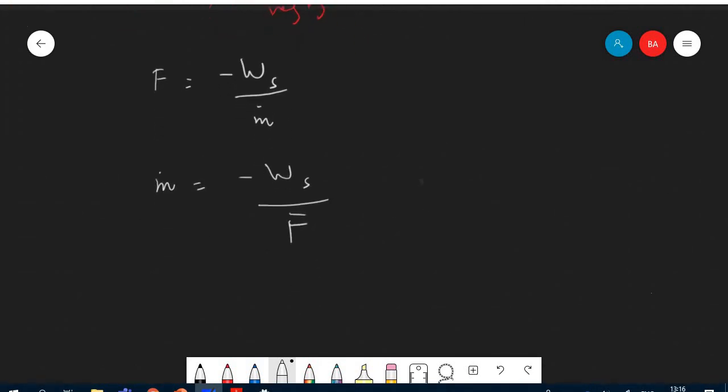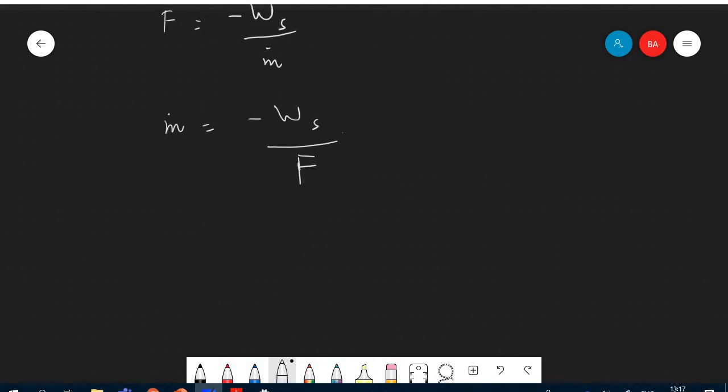And the whole story about m dot is all about the U term, right? The U term is the key, the velocity. I mean, it is the key of all of this, the solution of that. So to get my U term, I'm just going to do my substitutions here. So m dot is rho into U into the area, right? And my area is pi d squared over 4, so I'm going to just do everything in one go, is equal to minus WS over F.